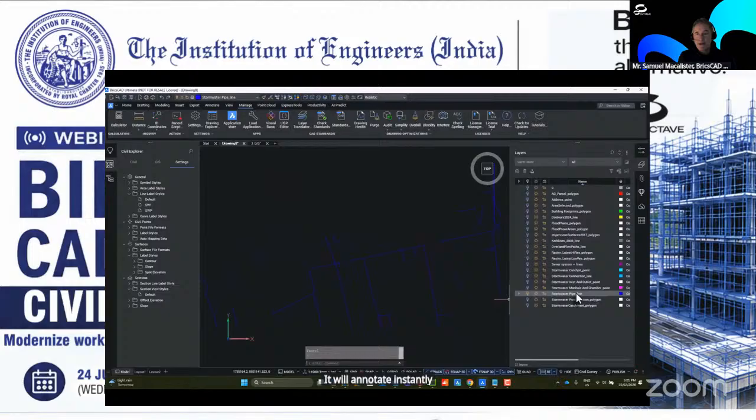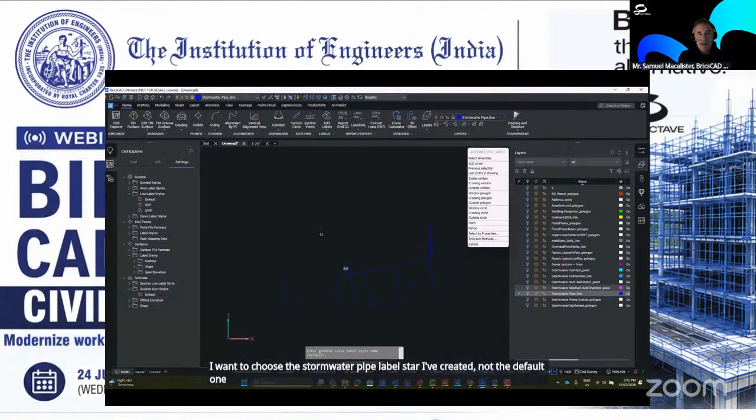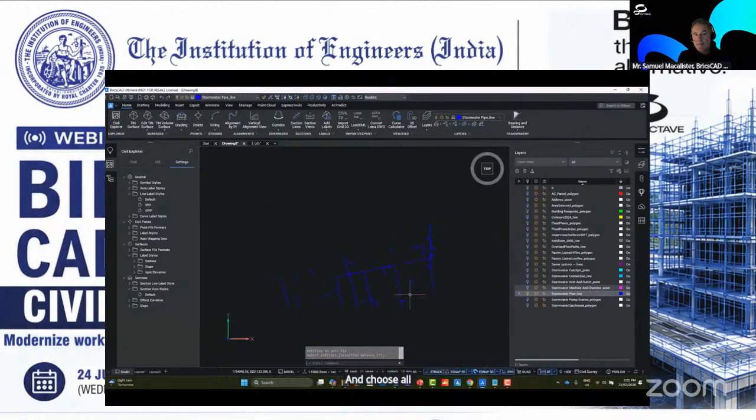So I'm just turning off the other layers and going to my line and label styles. I want to choose the stormwater pipe label style I've created, not the default one, and choose all that line work. And now instantly it's gone and annotated it for me and added some arrows.